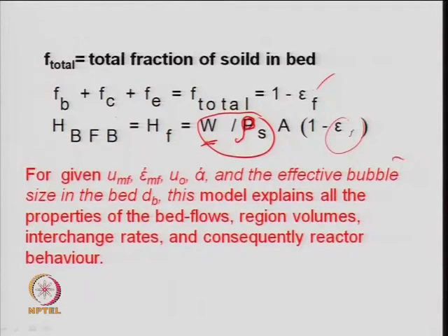So, these are known basically in the model, a property, and once you know this, then you can very easily define the hydrodynamics, bed flow, flow regime, interchange rate, that is mass transfer rate, and then finally, you can correlate it with the height of the bubbling fluidized bed. So, that is a fluidized bed reactor design.